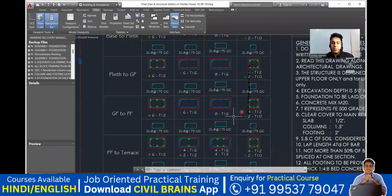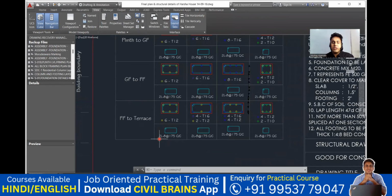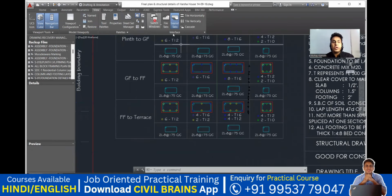So everywhere in this particular building, you're supposed to use a 2-leg stirrup. Why is it called 2-leg? Again, the reason is very simple, because this is how your lateral ties look. This is my one leg, this is my second leg, so it's called 2-leg. Along with that, if I provide another 2, something like this, then it becomes my 4-leg. Why is it 4-leg? 1 and 2, 3 and 4, it becomes a 4-leg. But here it is 2-leg.